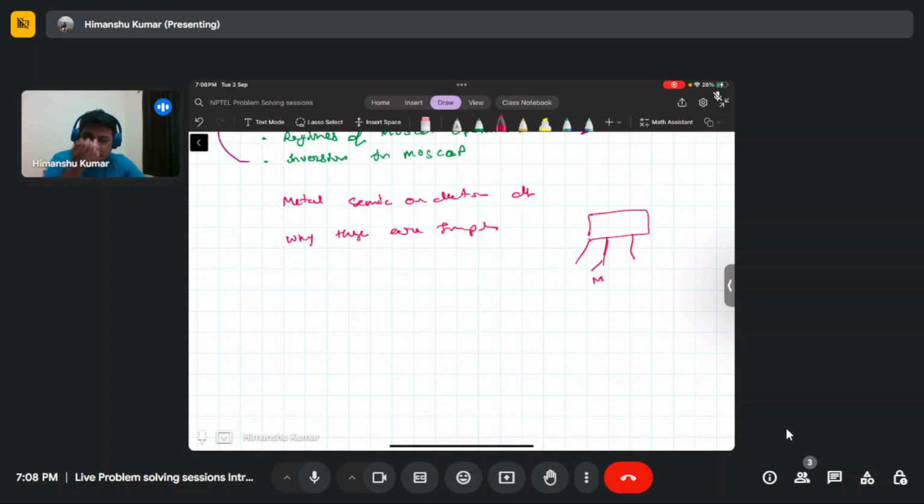You can't use a semiconductor because it has comparatively higher resistivity, and if you want to route a signal over a larger distance, or even at the wafer level from one device to another, you want to use as low a resistance as possible.